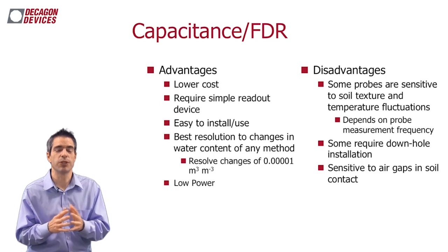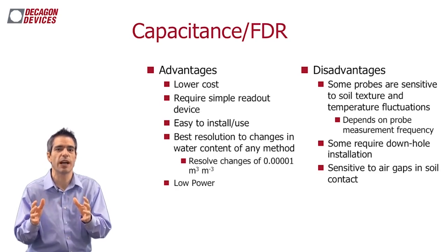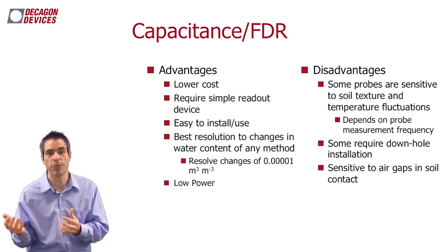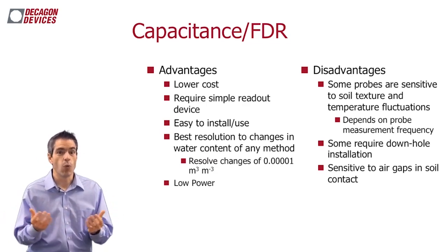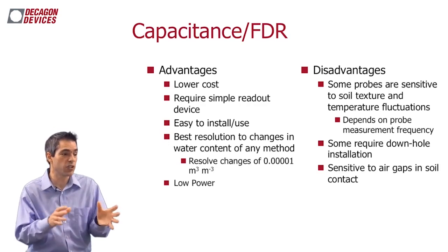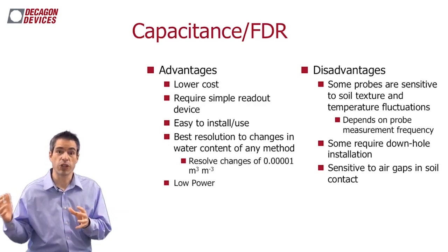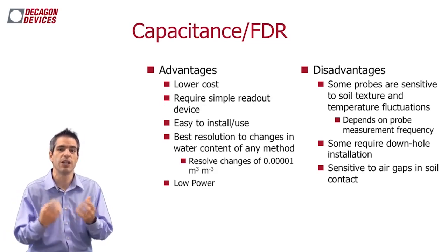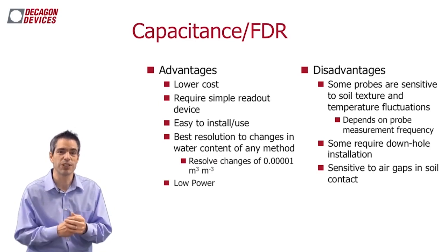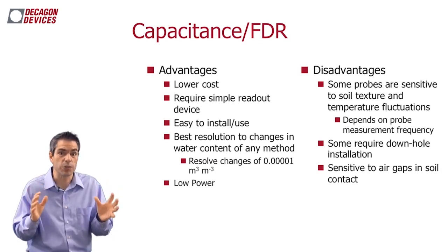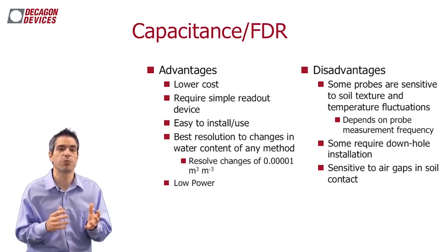Now, some of the challenges with FDR sensors are a little bit difficult to talk about because there are a lot of FDR capacitance sensors out on the marketplace. So some of the things I say apply to some and not so much to others. One of the reasons that capacitance sensors in particular have got a bad name in some markets is that originally, when Clark Topp took on this idea about the charge storing ability being measured with this dielectric permittivity, many said, hey, that's great, we'll just put a sensor to be like a capacitor right there in the soil, and then we'll make this measurement.